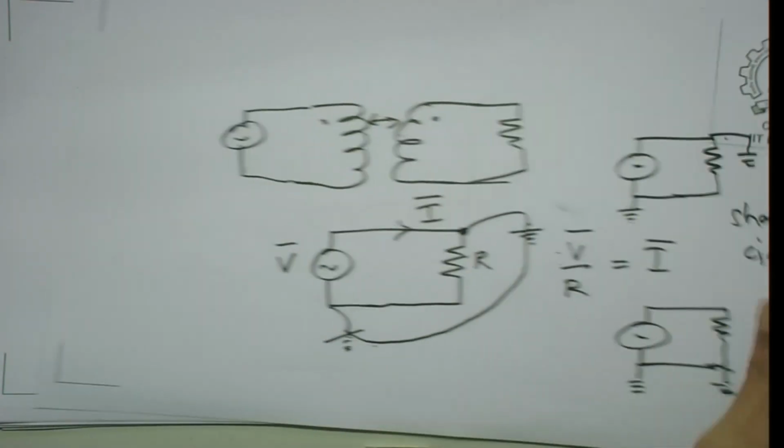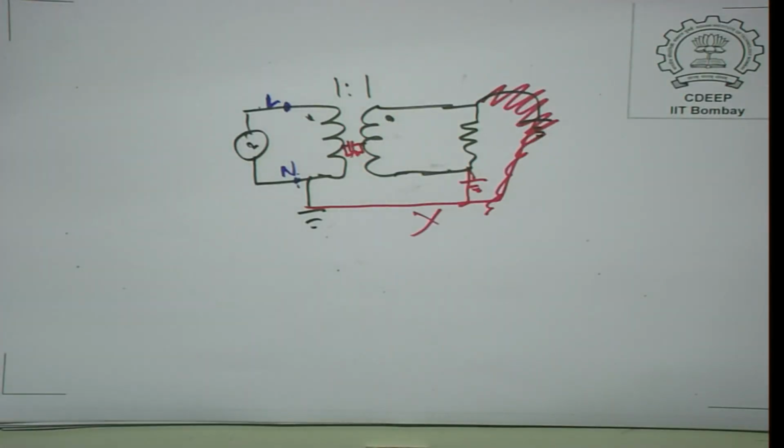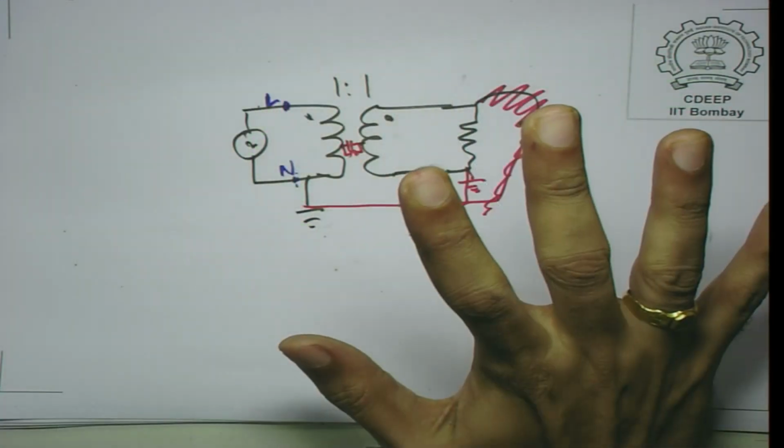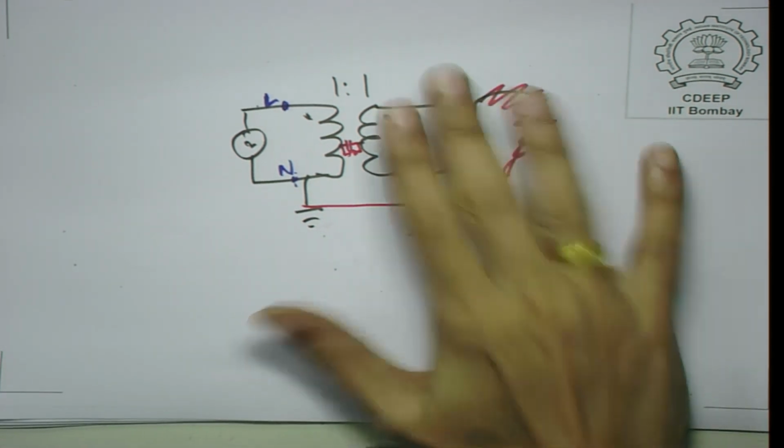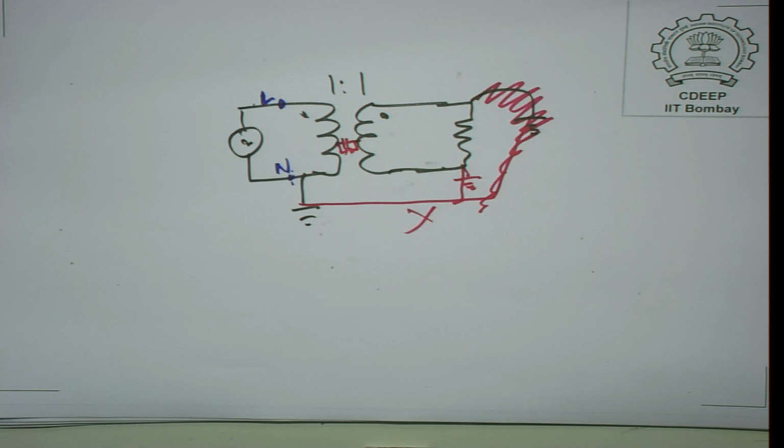These kinds of situations do not occur normally, but you can actually provide an isolation between the signal circuit and the power circuit, or circuit A and circuit B, and keep them isolated through a transformer. Connecting them together with a transformer will not cause inadvertent current flow, as I have shown you in this case. So, there will be no inadvertent current flow. If you have isolation, there is no danger of this happening. So, in certain circuits it is important to have this kind of isolation. Transformers are one way you can have isolation.